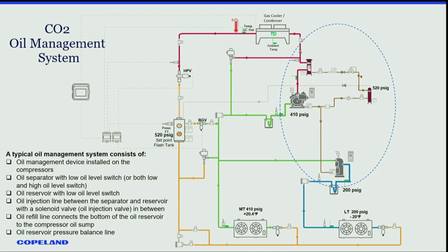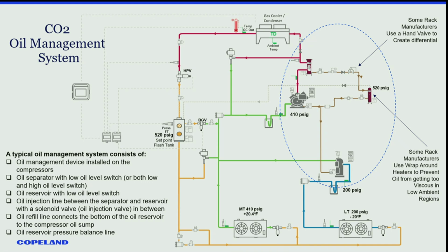That scenario I talked about, low differential for the medium temp compressor, even if I've got 480 pounds here, it's not going to affect my low temp compressors because I've got 200 pounds there. I've got lots of differential on my low temp compressor. It's the medium temp that you may be asking about, okay? And some will put heaters around the reservoir, especially as there are a lot more outdoor units these days, to make sure that oil stays nice and fluid and not too viscous.